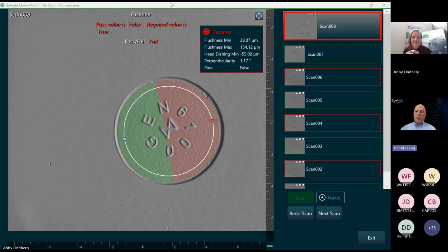Composite holes obviously often are not as clean, especially in a sustainment or an MRO, so a composite hole that's been in service. And damage presents differently. So the surface of a composite, if there's no paint on it, can actually be sort of clear, and then you have matte underneath. In the case of, say, an aircraft skin, you might have an ESD layer for electrostatic discharge abatement, whether that's lightning strikes or other things, to protect the sensitive electronics on the aircraft.